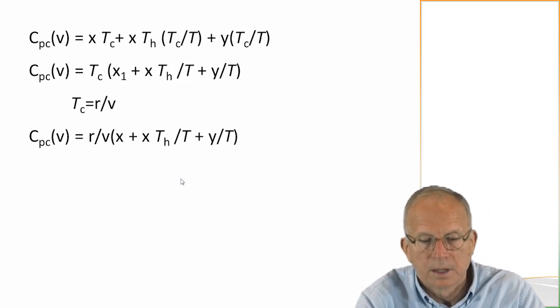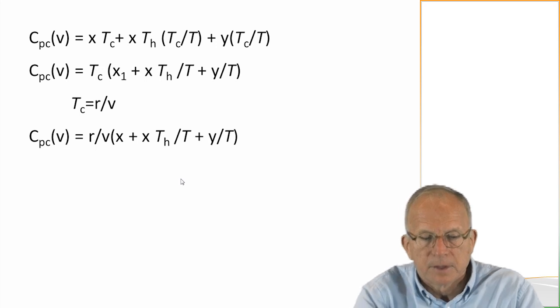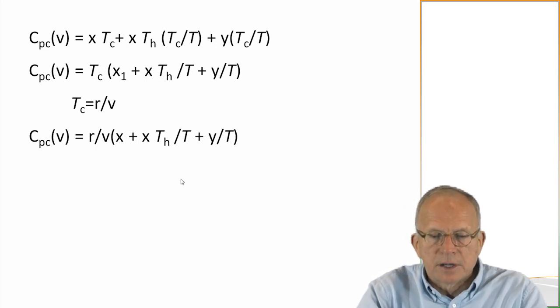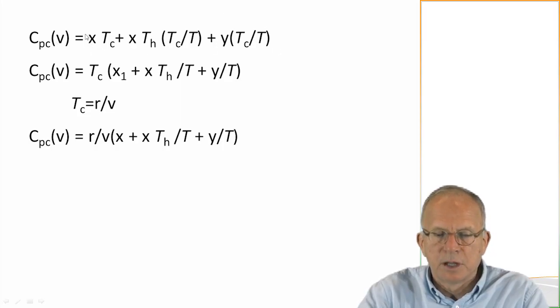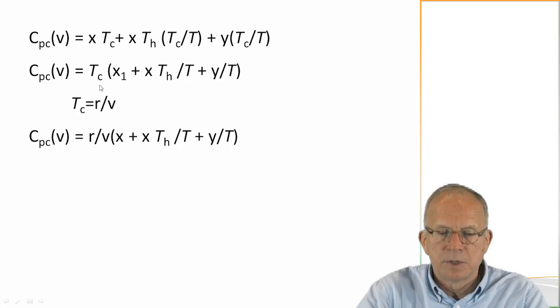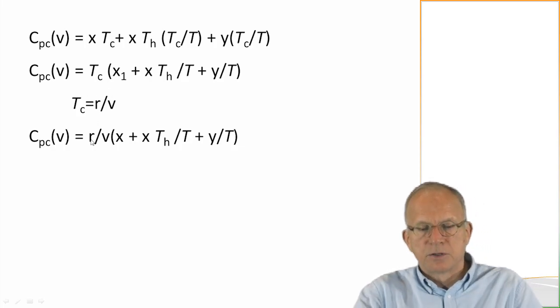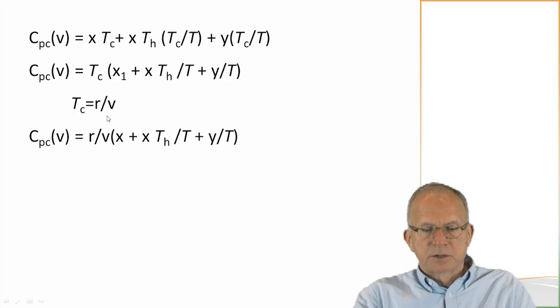All are going to vary with cutting speed. So we need to rearrange here and make some substitutions. So first, here we've substituted in the different things that are a function of speed. We can take out now the tool life, but we need to put that in terms of speed, so that's the distance traveled divided by the speed.